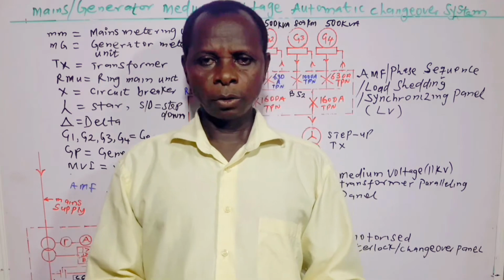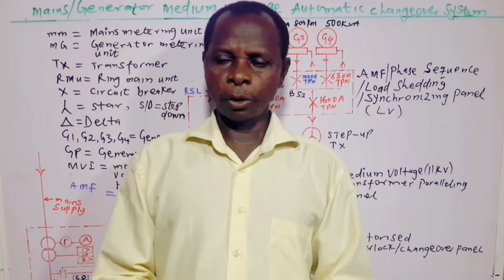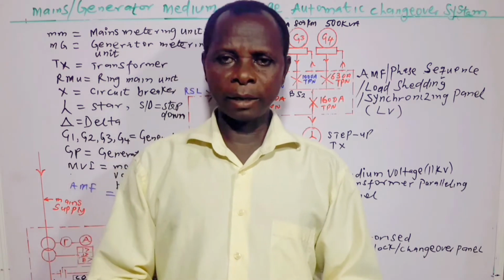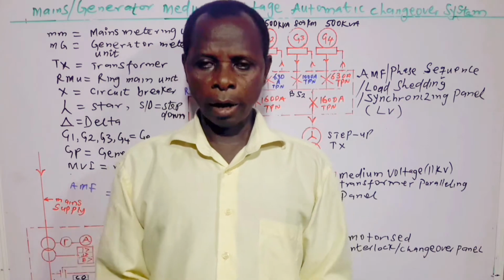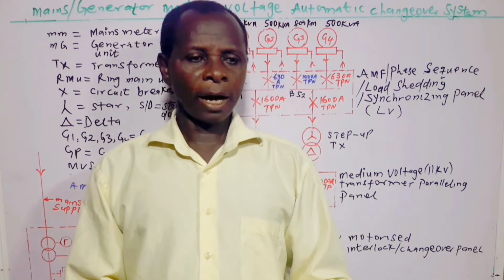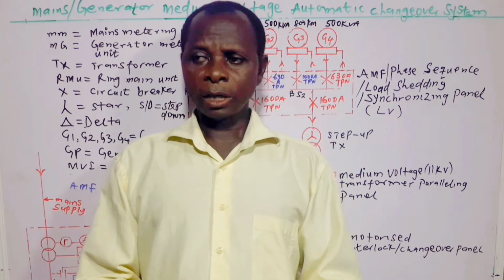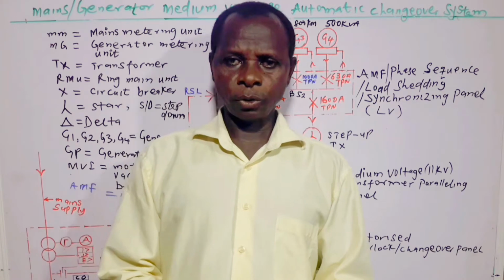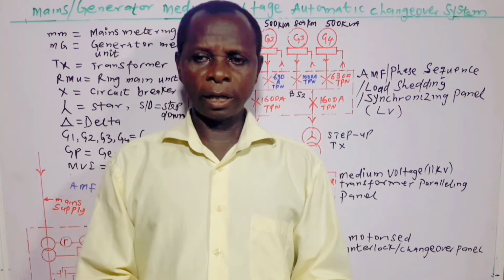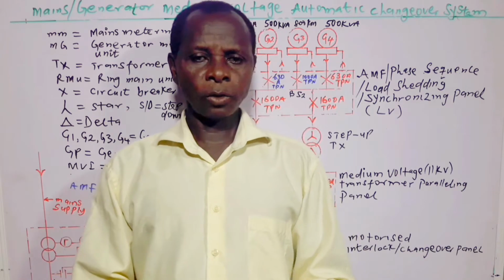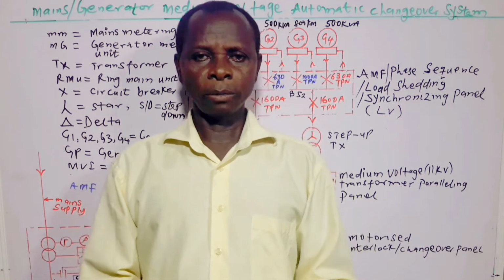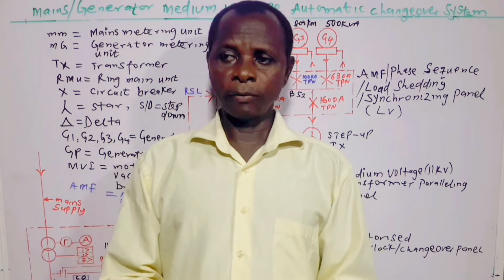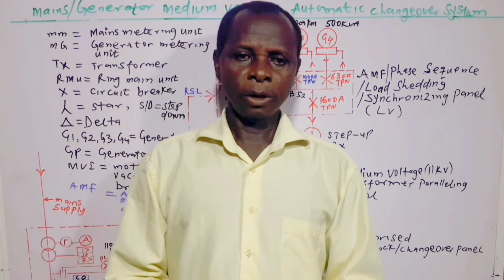Yes, I mentioned it. So today we are talking about the magnitude of the load itself, that is the power rating, the overall power demand, as well as the current. So if the design current at low voltage is such that the circuit breaker to be used, its current rating is not readily available in the market, then there is no other option than to move on to the use of the medium voltage, which is 11 kV or 33 kV.